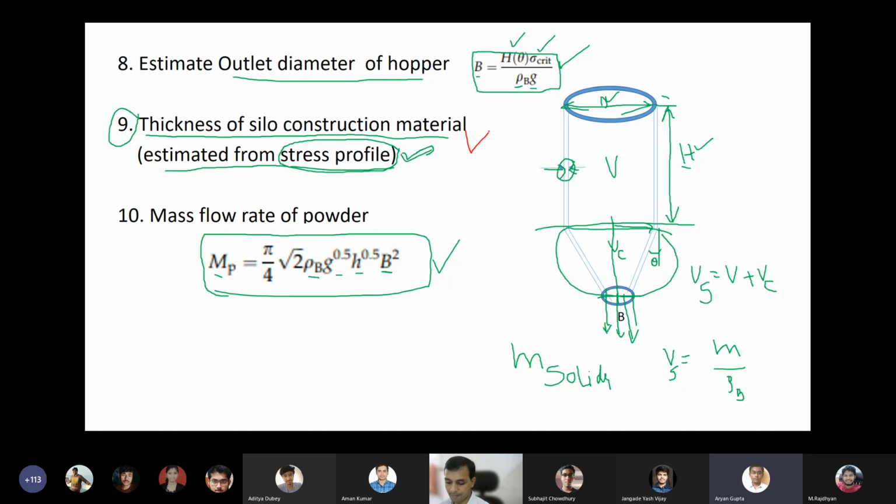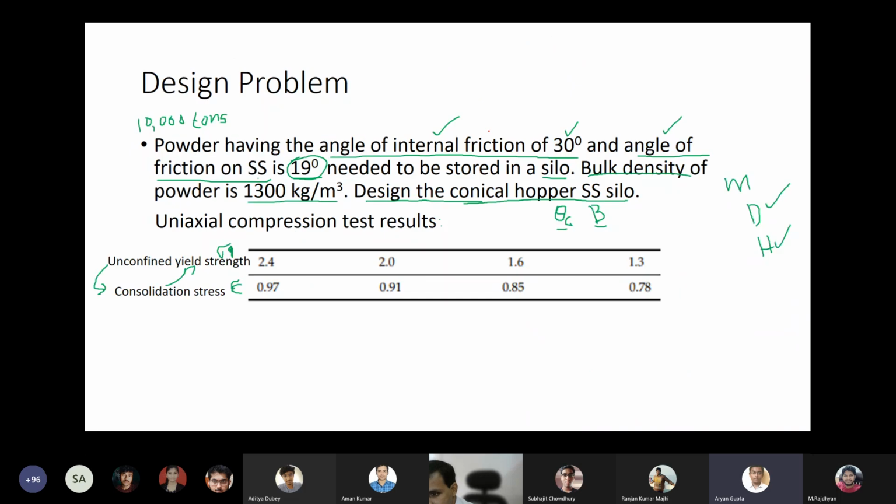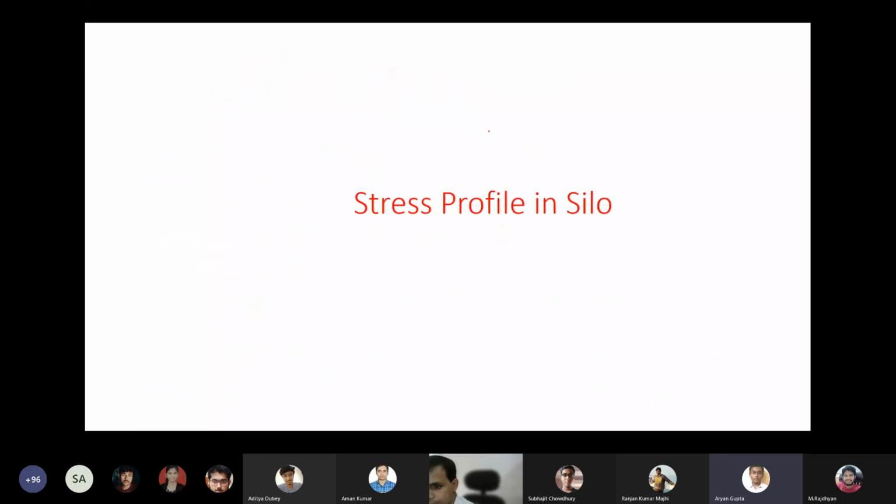Yes, please. I was asking, although it is impractical, if we were to maintain the compactness at each and every step, releasing the flow by a little amount and maintaining compactness, then we would get the curve that the Janssen equation predicts, right? Although it does not suit the practical experimental flow curve we are getting.